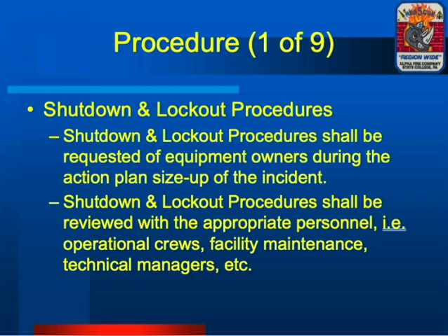Shutdown and lockout procedures shall be requested of equipment owners during the action plan size up of the incident. So what we're saying here is we just want to talk to the people who generally work with this piece of equipment and involve them in the size up and really have them kind of guide us as far as how to shut down a piece of equipment.